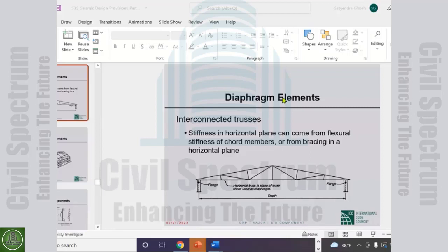That is deflection or displacement. The drift is interstory displacement. Drift is deflection at the top of a story minus the deflection at the bottom of the same story. That's very, very important, okay? Deflection is for a floor level. Drift is for a story, and drift is deflection at the top of a story minus the deflection at the bottom of the same story.